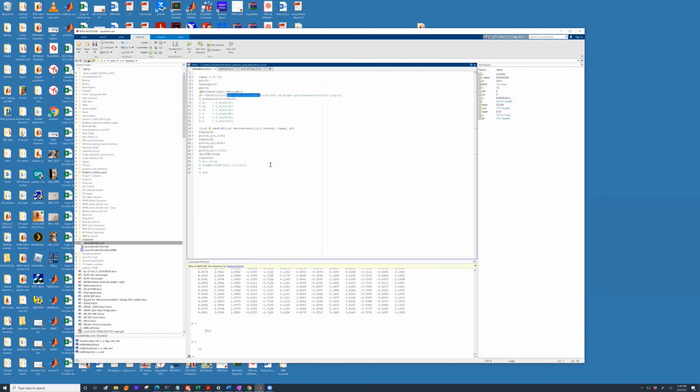Okay, correct. If that is the error you are getting, the Robotics System Toolbox is included free of cost in your Matlab. So what you need to do is go to Home, click on Add-Ons, then click on Get Add-Ons, and then get the Robotics System Toolbox, and it will be installed immediately for Matlab. So if eul2quat is not running, that means you may not have the Robotics System Toolbox installed. For that, again, you need to go to Home, go to Add-Ons, and get Add-Ons.